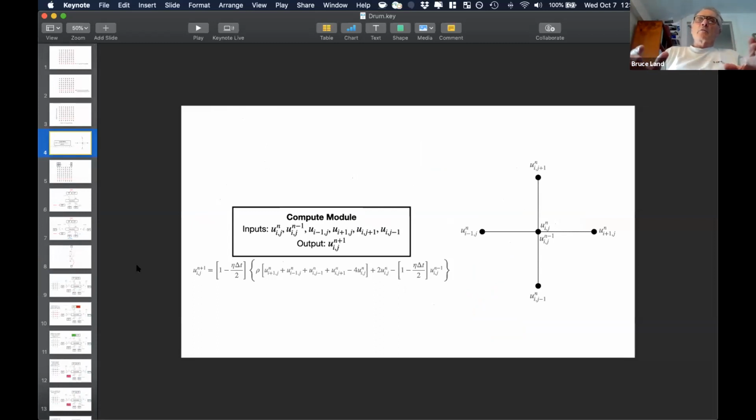As you go down to a rho of a 16th or a 32nd, then you will see a sine wave with 16 or 32 samples on it, and it looks more like what you expect as a sine wave. As you go to a bigger drum, the frequency drops because the propagation distance is bigger. So a drum twice as big will have half the frequency, in which case you could increase rho a little bit.